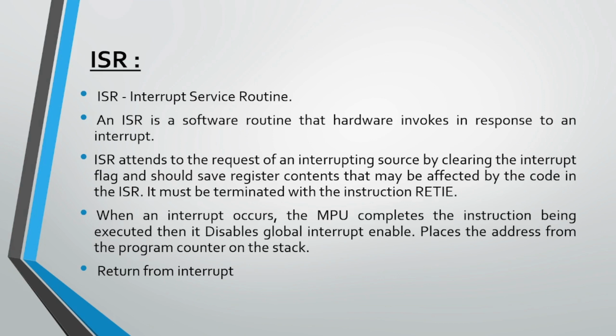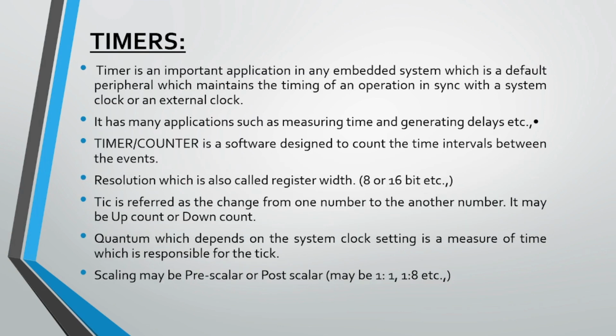When an interrupt occurs, the MPU completes the instruction being executed, then it disables Global Interrupt Enable, places the address from the program counter on the stack. An ISR is a software routine that hardware invokes in response to an interrupt.